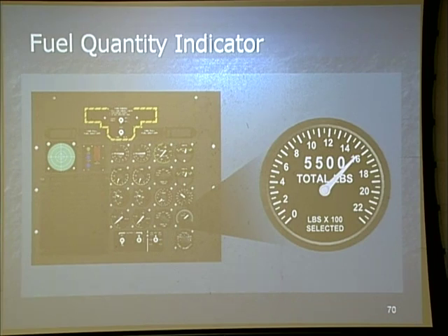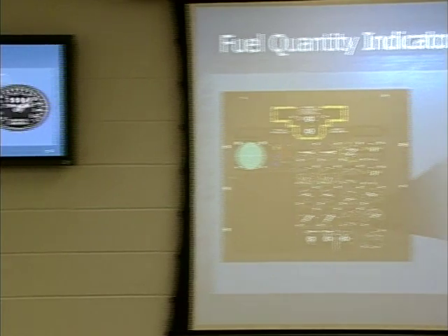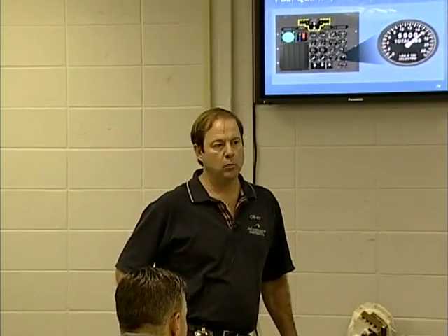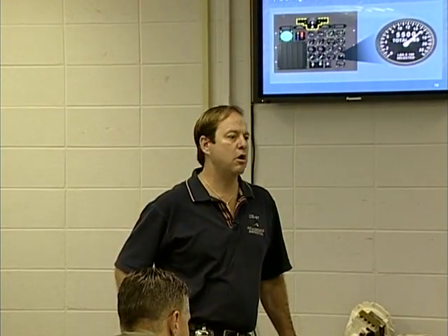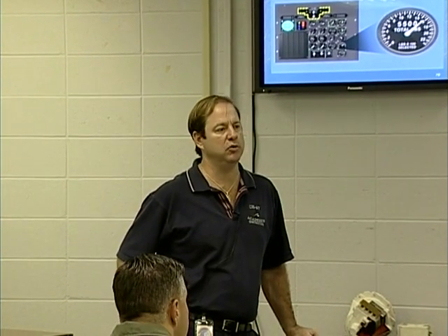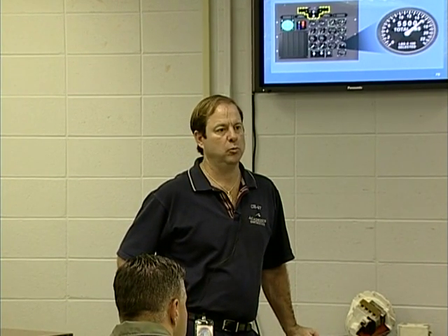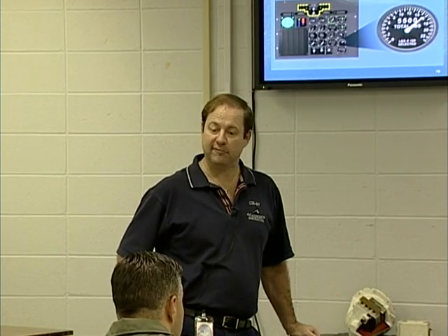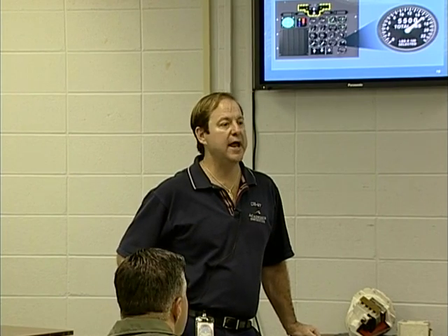How does your fuel system work in your car? Is it a totalizing system? No. As you're using the fuel in your car, what's going to happen to that fuel indicating quantity? It's going to keep coming down, right? Now, what's the problem in this aircraft? What if the fuel in my aux tanks becomes classified as unusable? What will my totalizer tell me? That fuel is still available. That fuel's still available. So what would I have to do?